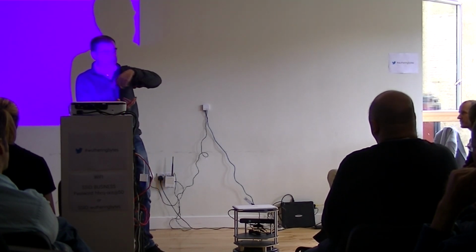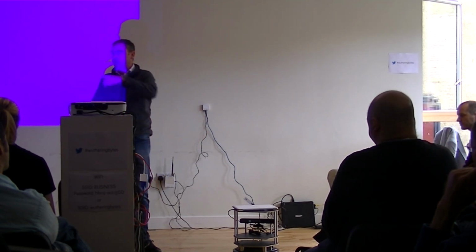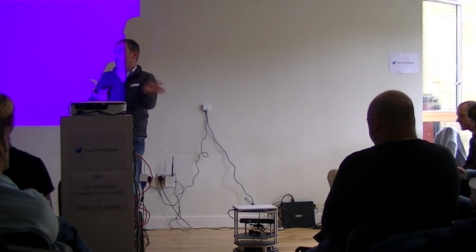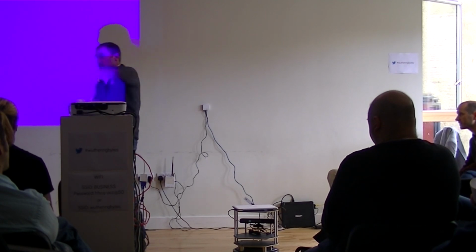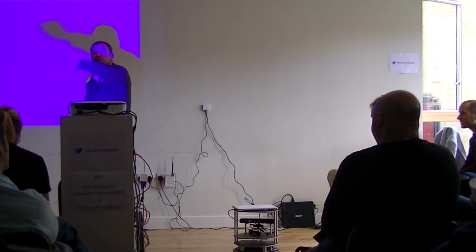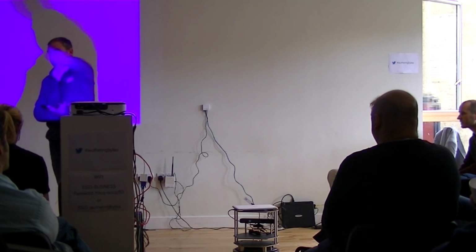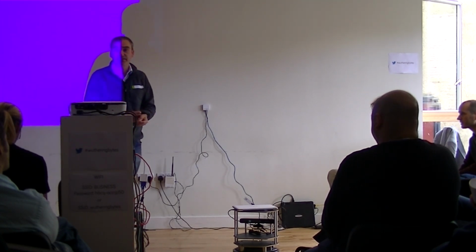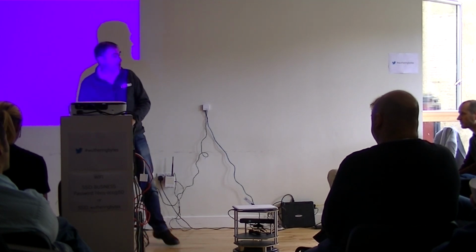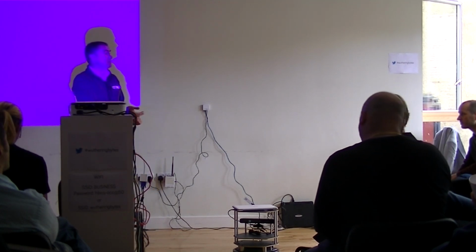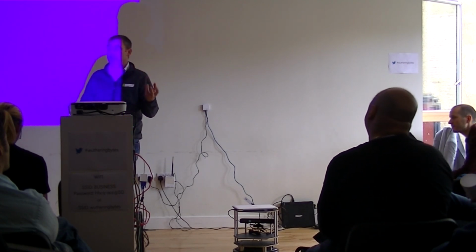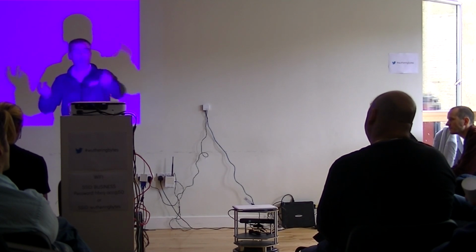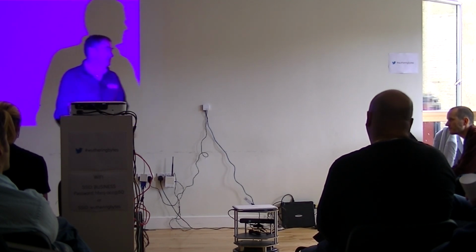There are things like laser scanners that do the same kind of thing as a Kinect, but they cost a lot more. They either go 360 or about 270 degrees, and the laser's scanning around quite quickly and giving very accurate distance. So it's not building up a big picture, it's doing a line, but it's much more accurate than the Kinect. For all the common ones that you can buy, people have written nodes. So if you buy a Hokuyo laser scanner, there's a Hokuyo laser scanner node. You launch it with the scanner plugged in and it just publishes the information. You could do exactly the same.